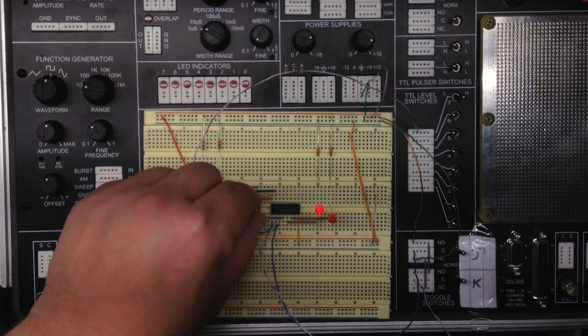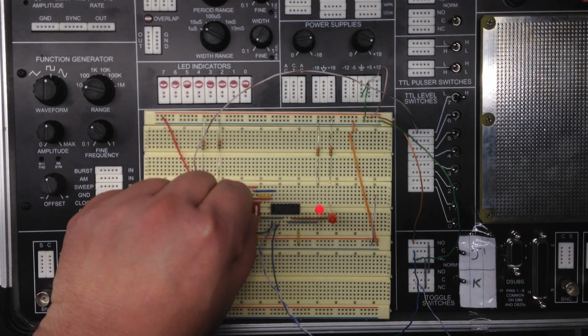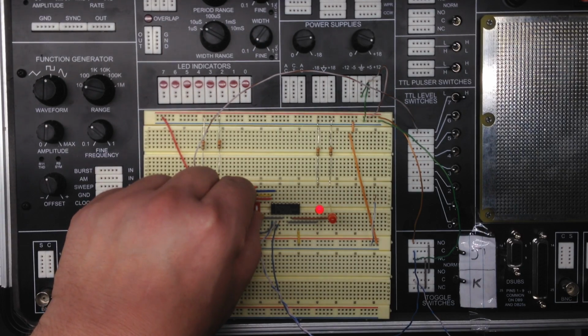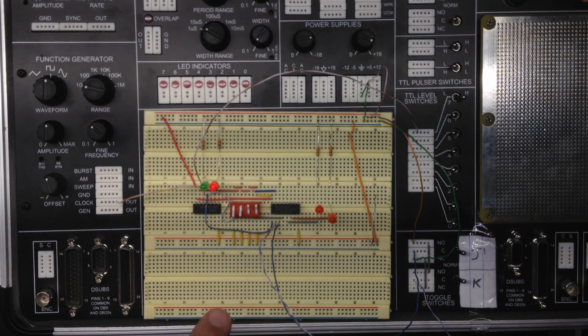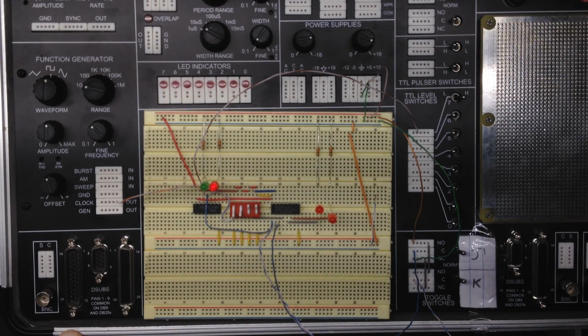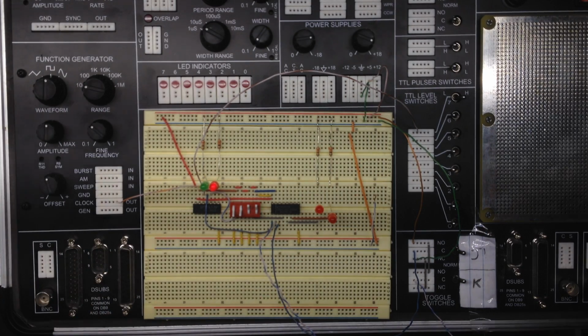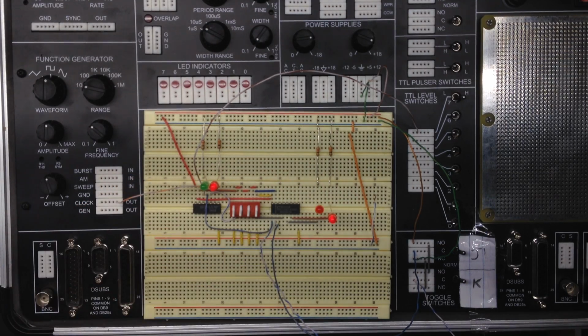Whenever we switch these to high, the note that we're given in the truth table is that this configuration is non-stable. That is, it will not persist when preset and or clear inputs return to their inactive or high levels. So we have both now set to high. We can see that we received a high on both, and we have a similar type operation happening here where there is a constant fight between Q and Q naught to take over which is high and which is low. So if we return both of these back to low, we're going to go back to whatever the current state was set on the switches, which was high on J and K, giving us the toggle, which we can see happening across the LEDs.